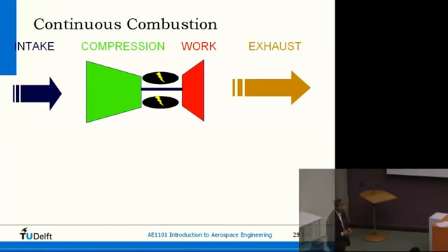We have a lot of radial fins there which actually compress the air. Before we ignite the fuel in the combustion chamber, we go past another set of radial fins, the turbine. This is the compressor, combustion chamber, and this is the turbine. And then we get the exhaust. What we do here is take off some energy that we produced in the combustion chamber to drive the compressor. And that's why we have the difference between the upper line and the lower line as the net efficiency. Here we take out the energy of the flow. If you have a turboprop, this is also your main energy generator because you connect a shaft to the propeller.